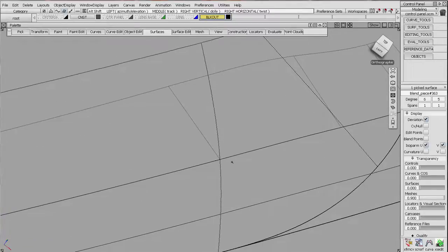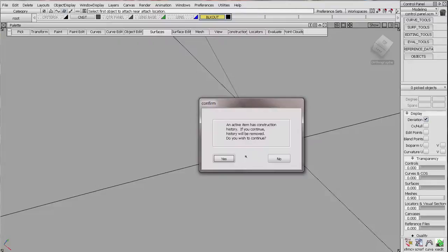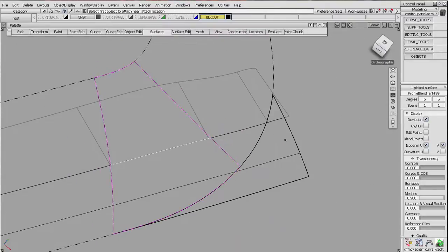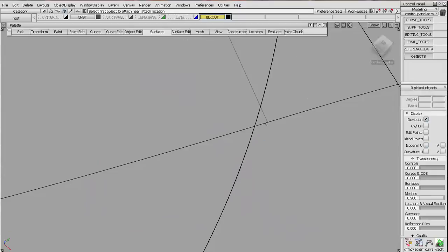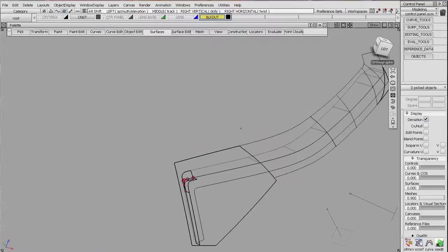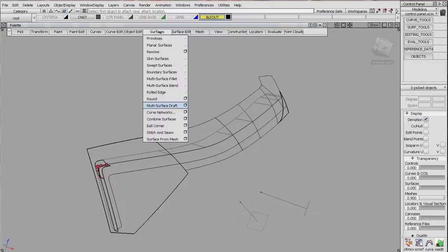Here we look good, and over here we have another little piece. This is some little cleanup that you can do, and every time you do this, you're eliminating a little sliver of surface, which eliminates continuity that you have to check. So it's a good idea. It also eliminates thin sliver surfaces that can cause issues transferring to other systems. Other systems don't like little tiny thin slivers everywhere.